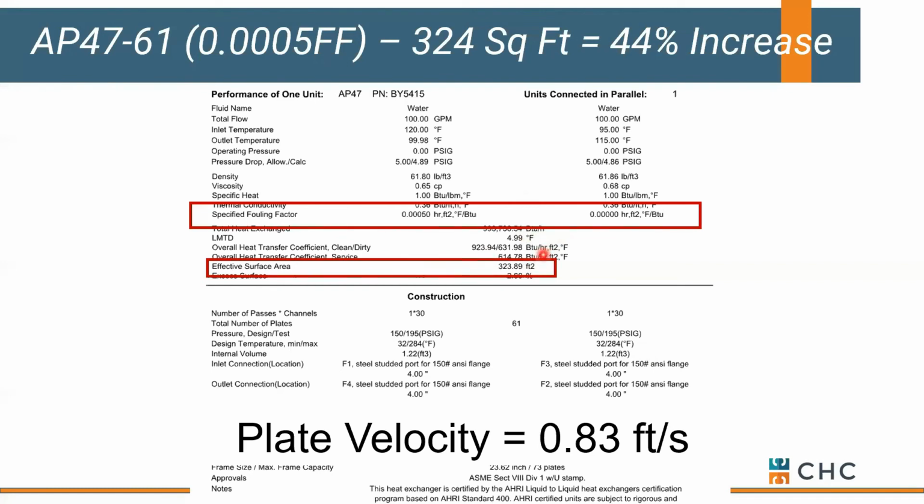Okay. No, best to ignore it. Honestly, that's what we tend to do in-house. If we see fouling factor applied, we will tend to ignore it because it makes conditions worse. And sorry, no idea. No problem. Listen, this is why we're all here talking about it. So let's talk about another option besides fouling factor.